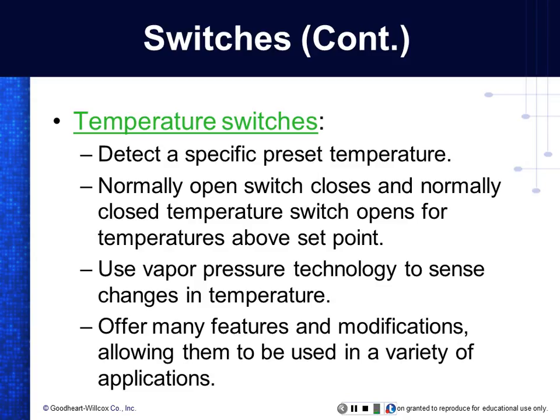There are some switches and things that are interlocks because they don't want you to be able to get your hands in things, and they force you to put your hand in two different places so they can't be in the middle. So if a punch comes down or a shear or something, they don't want your hands in it, so your hands have to be out here, and it won't operate until both hands are right here. I've even seen some that have interlock guides where you push a piece of metal in, and when you step on a foot switch, it pulls your arms backwards. So there's all kinds of safety switches.